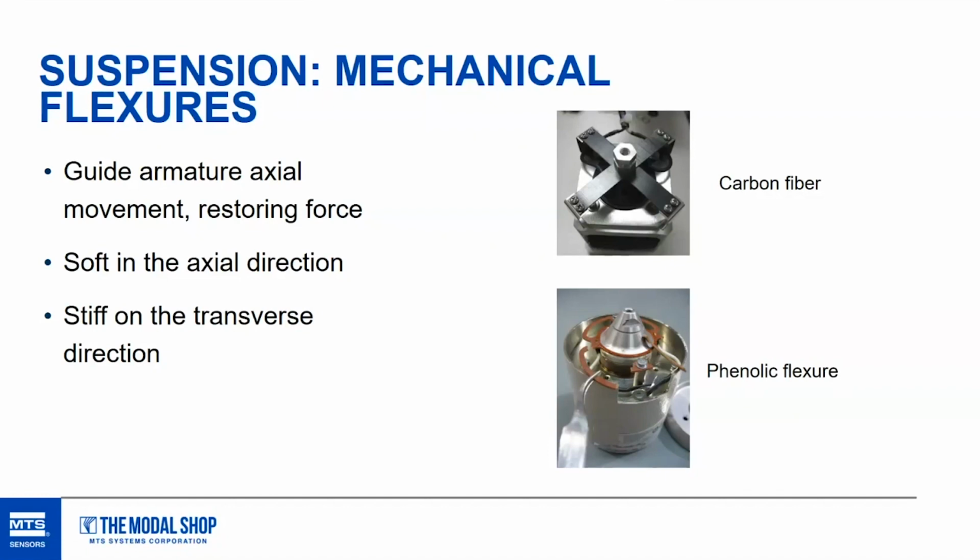So you want to keep it stiff in the transverse direction, but you want to keep it soft in the axial direction so the shaker can move.